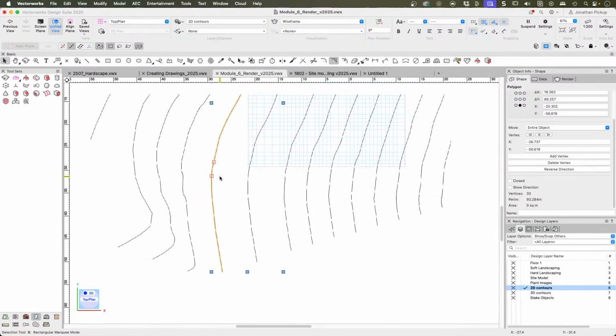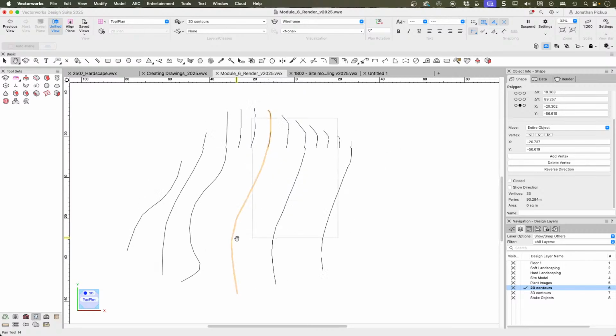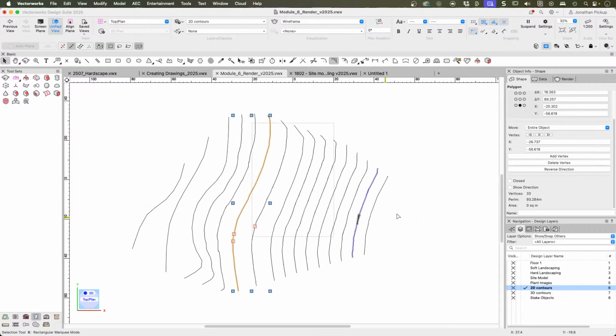So one of the things you should really look for is making sure that you simplify these polys. It'll really speed up the way you create your data. And on polygons where you've got thousands of data points, this can be a real time saver. Also, if you've got a lack of memory or processing power in your computer, Vectorworks processing so much information can appear like Vectorworks has crashed, but it hasn't.